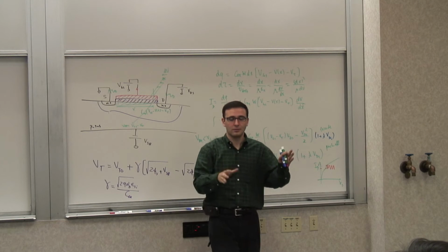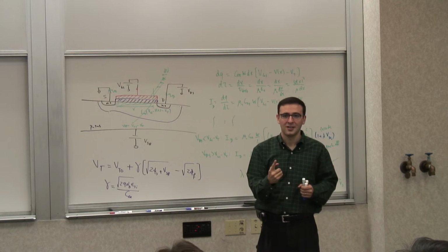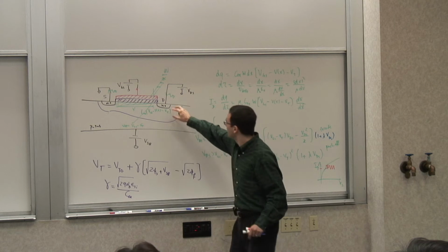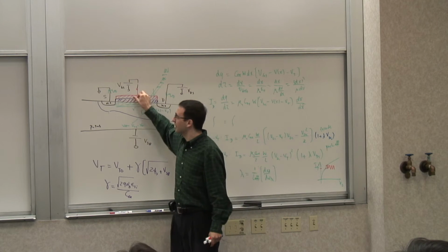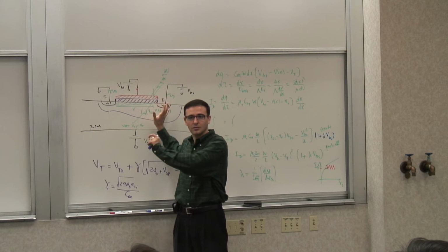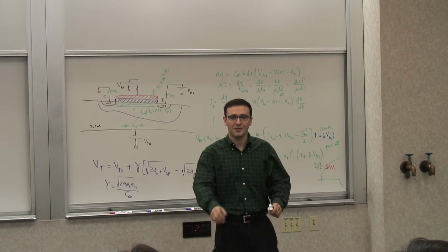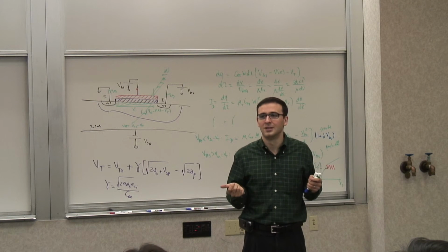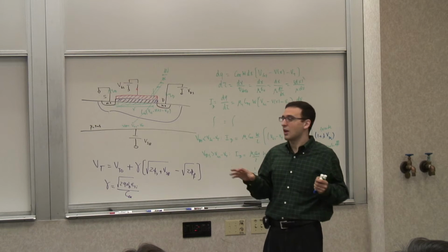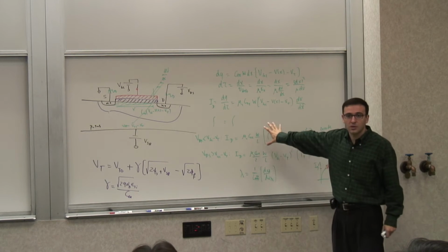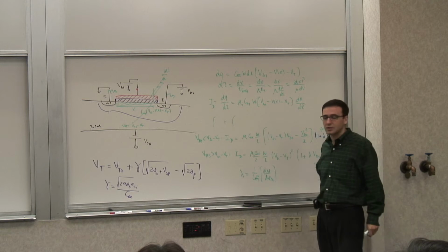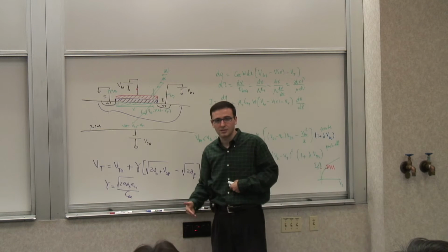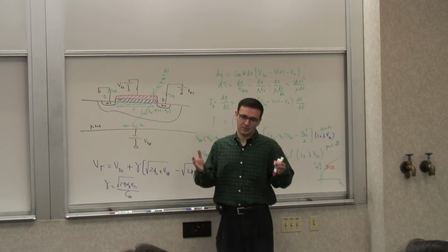But all you can solve with those things is one transistor. So you can design a transistor, well, this is the dimension, this is the distribution here, this is the thickness of the gate, this is the material, blah, blah, blah, and let it run for a couple of hours and it spits out what the IV characteristic looks like. Which is a lot more accurate than our first order model, obviously, because it solves the differential equation. So there are different levels of simulators. But that solves one transistor.